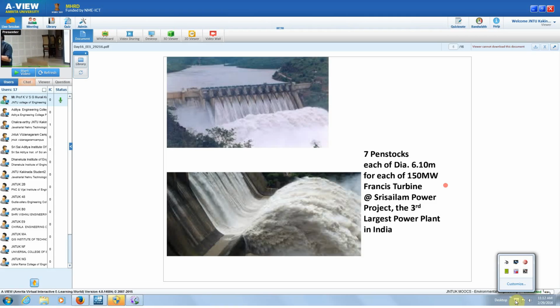See, turbine and pump, if you see the components, are more or less the same. For example, the rotating element in case of a pump is called an impeller. The rotating element in case of a turbine is called a runner. Structure-wise both are more or less the same. Both are vanes of particular size and shape, and both are surrounded by a spherical casing. Internally, there is no great difference between turbine and pump; both are more or less identical.